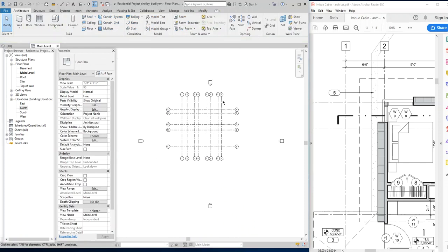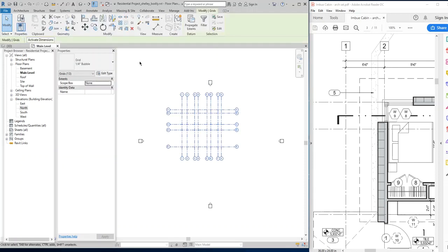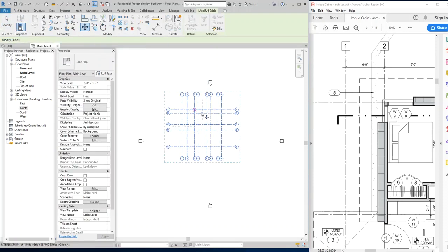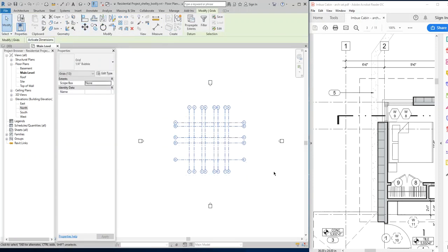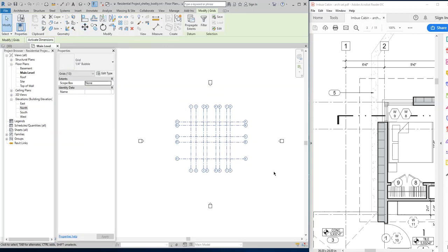Okay. And it's a little bit askew, right? It's a little close to this, a little close to that, further away from here and there. Doesn't really matter. The grid system is working. I could move these elevation markers if I needed to, or if I'm really picky about this, I could grab it because no walls have been generated. I could use the move tool and move it into the center, or nudge it with my arrow keys to where I wanted it to be, right?